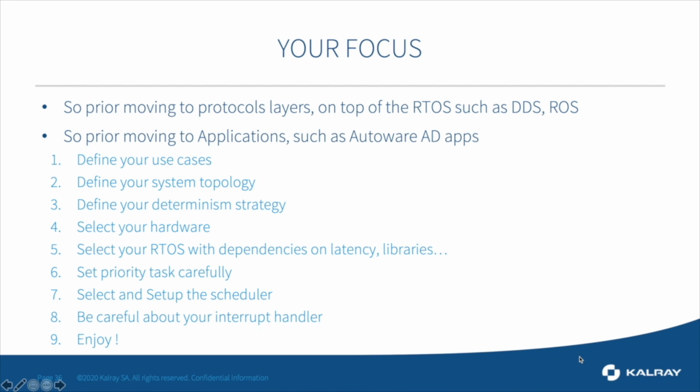Select your hardware, or take the hardware that you have or have access to, and the RTOS similarly, and start to map your topology to your determinism strategy with the capability of your hardware and your RTOS. Define your tasks carefully with priorities and the scheduler methodology you will have. Take care about the interrupt configuration and enjoy working with all these tools.